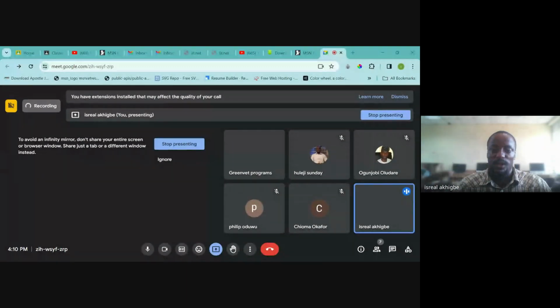That particular belt is the V belt. Because of the nature of the V belt, it is designed to be used with a pulley that has a V groove. You consider a groove as a slot or guideway in which that V-shaped belt is to sit. As a result, it sits perfectly with some level of contact surface area. Friction is what holds it together in place.